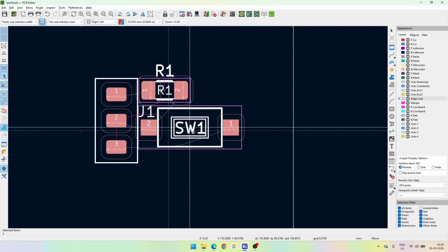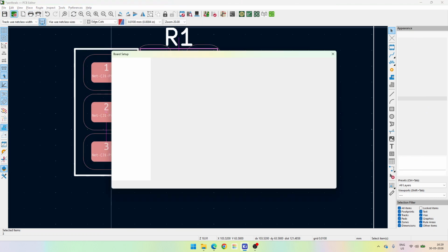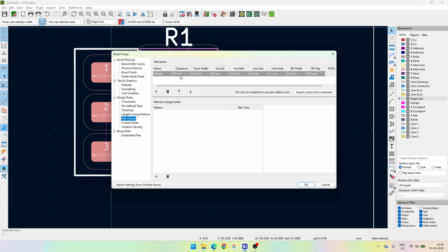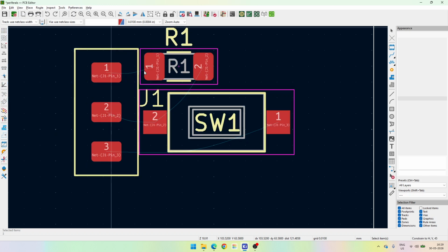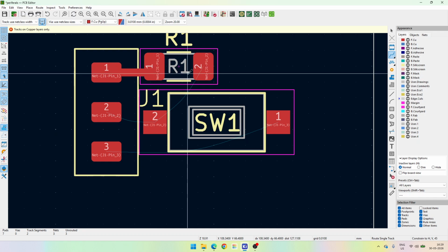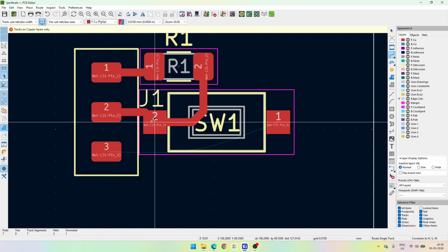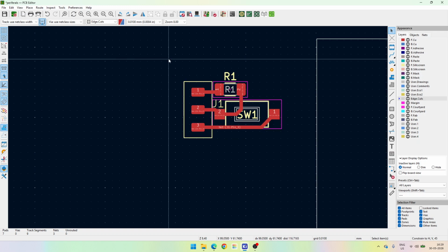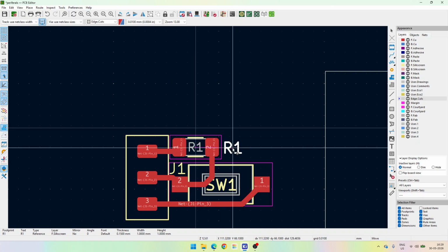So having done that, one more thing that we have to take care is the net classes. The net classes, I'm making it pretty big here. The clearance is 0.5, the track width is also 0.5 of an mm. So here when I start routing, it becomes easier for us to get these components routed, right?